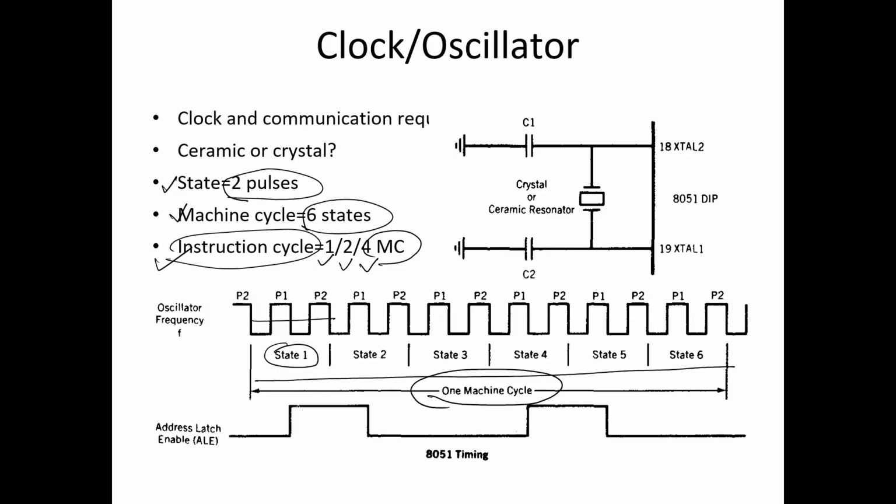As per these timings, address latch will be going high and going low. When it is going high, the address bus will be activated. When it is going low, the data bus will be activated.